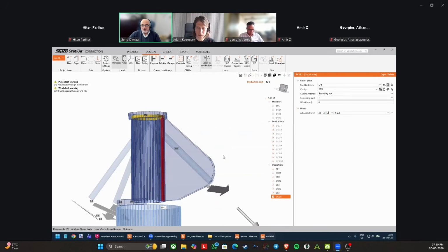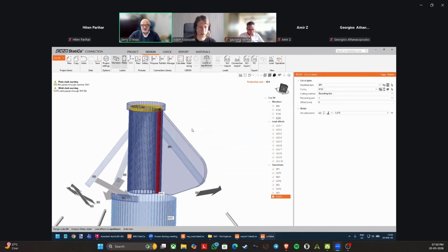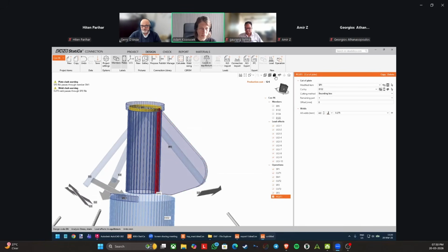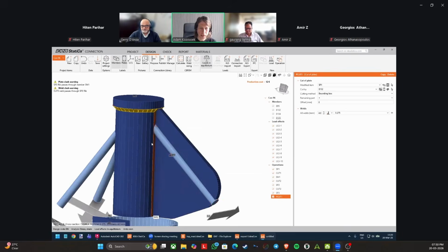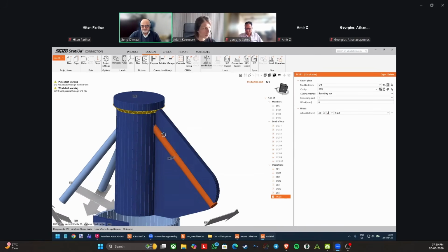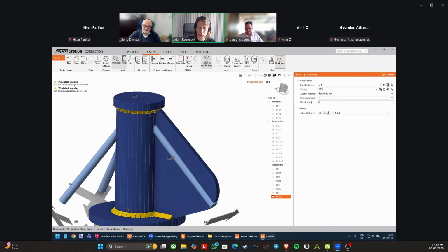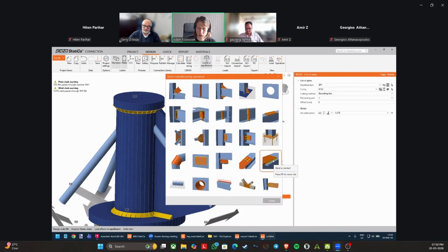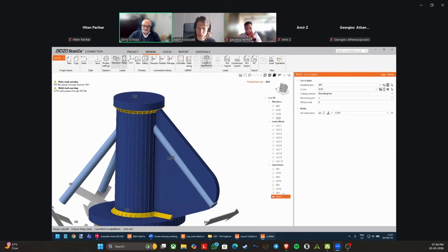Okay, so sorry, a question, Adam. Yes. So you suggest to draw the plates bigger, so then we cut them later. Yes, exactly. It depends on your approach, what you like. Either create the plates bigger, or what you can do as well is not to cut the plates, but set them exactly in the position that you like, and then don't use the cut of plate, but rather use only a weld. Okay. Yeah. But my approach, it seems simpler to cut them. That's why I was asking.